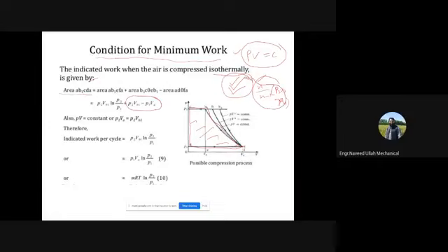For the isothermal process, it is like this. It is actually this one. You can look up where it comes from, and what the area under the curve equals for the different processes. Anyway, it has proper mathematics; they are basically using integrals etc. to derive this formula. The work will be P1V1 log of P2 by P1. That is your work in the isothermal process.